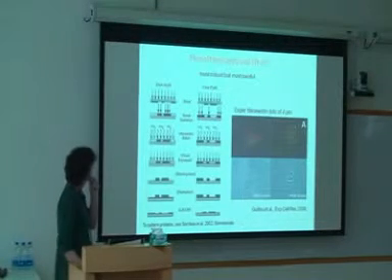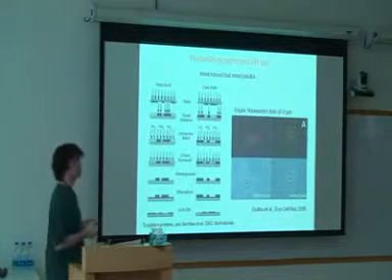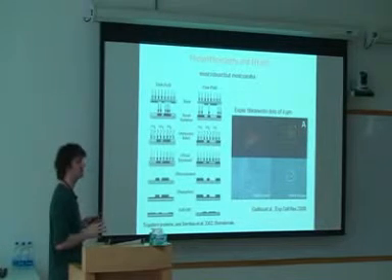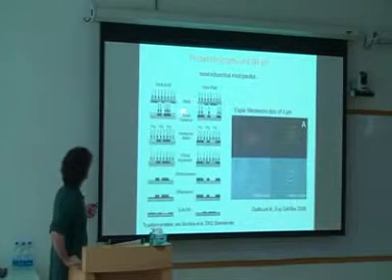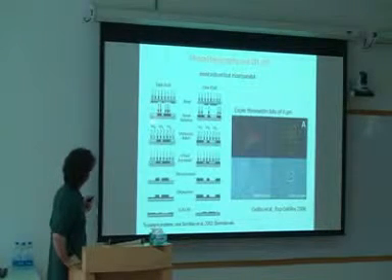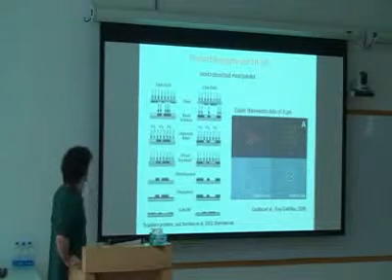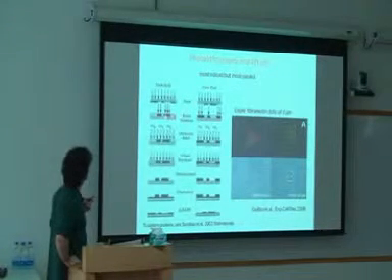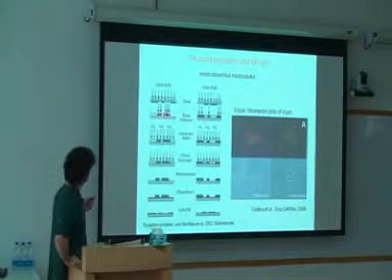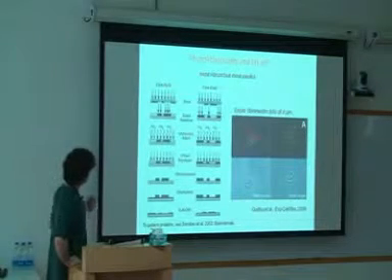This technique is, I think, the very first technique that people used to make patterns, because it's really directly photolithography. It's called photolithography and liftoff. So what you do is what I showed you before. You will cover your cover slip, usually your glass substrate, with this material which is sensitive to UV.